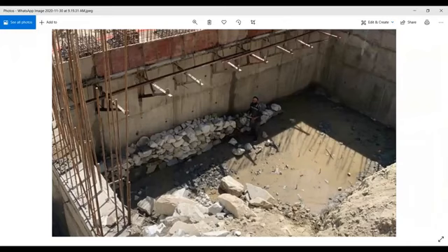so this filter media, the water passes through this filter media, it goes into the weep hole and comes out on the other side of abutment, so that if this is not allowed, then this water will create undue pressure on the abutment, which we do not want. We want the water to flow, and that is why this filter media is put, because otherwise this soil will clog the weep holes, the water will not be able to come out. So you put this filter media thing and weep hole is there.